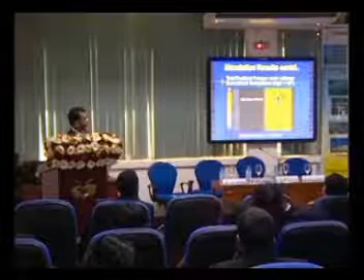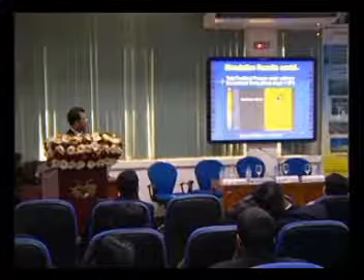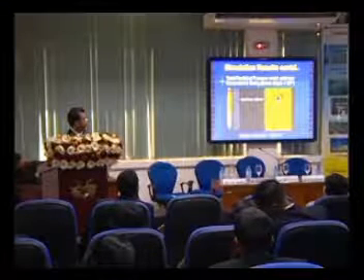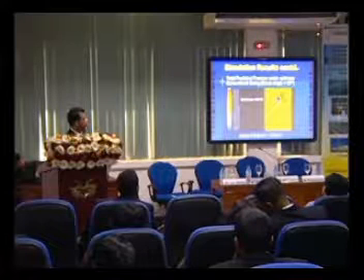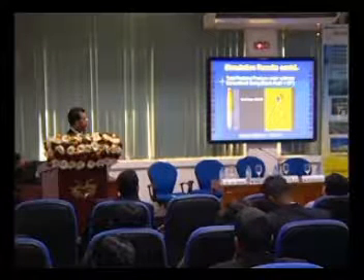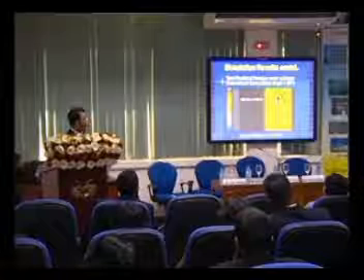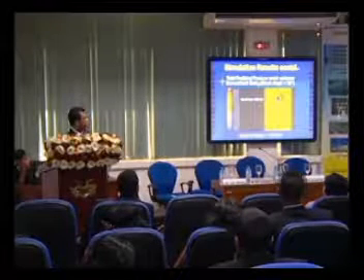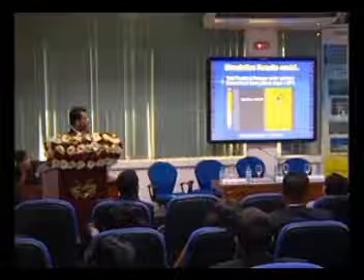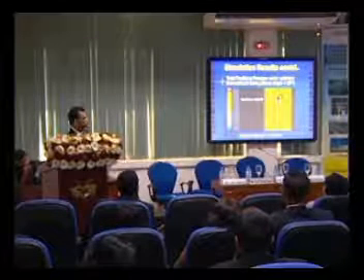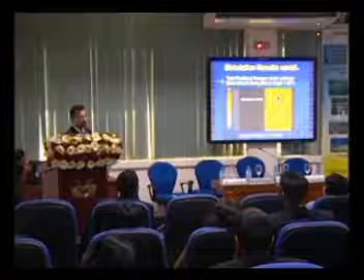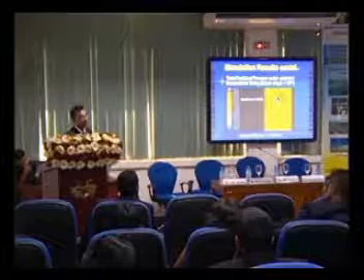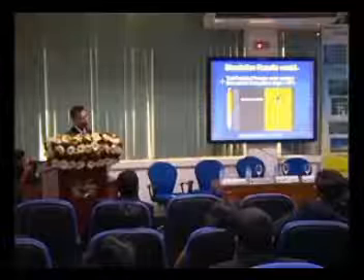This is angle 30. You can see there's a high pressure zone here, low pressure zone here. So the side force is in this direction, in the direction of the seam orientation. So the side force is 0.64 Newton for optimum conditions, and that optimum speed is 112 kilometers per hour. Later on I will tell you why this value is low. Conventional swing, whatever the commentators say, is only a tool that can be used by medium fast bowlers, not by fast bowlers.